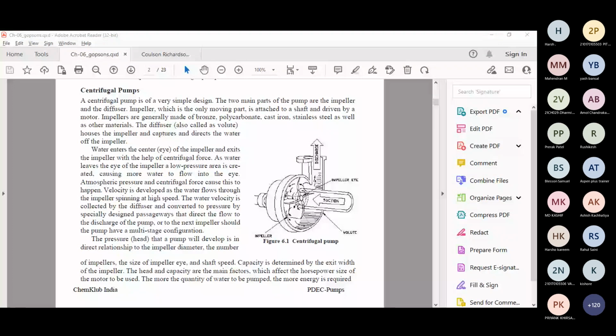So when to use which type of impeller? Whenever you have some solid particles or some slurry, you should go with the open impeller. With a high amount of solid content, you can go with the open impeller. Whenever you have a clean fluid with no solid percentage, clean organic mass or clean solvents, basically methanol, heptane, benzene, toluene, for clean solvents with no solid particles at all, you can go with the closed impeller.